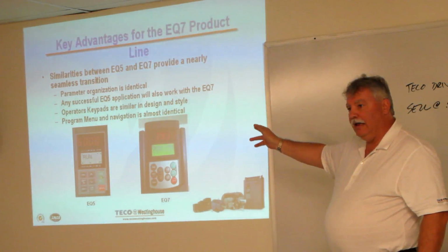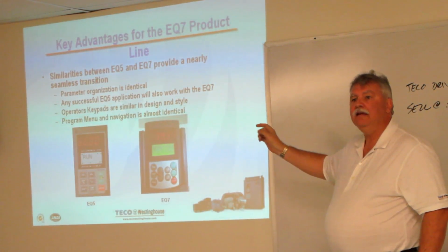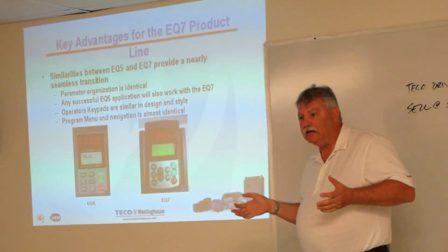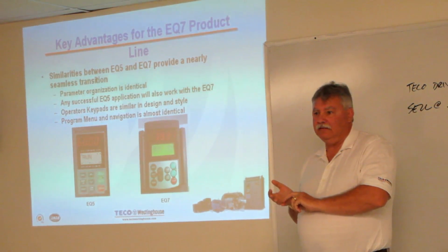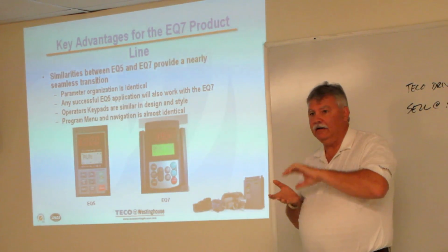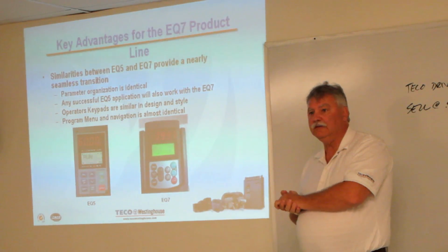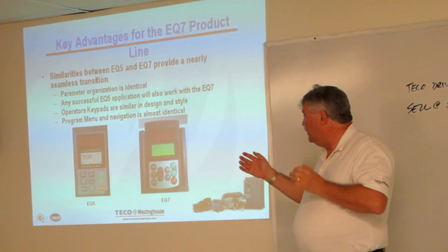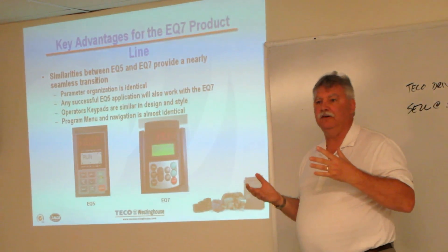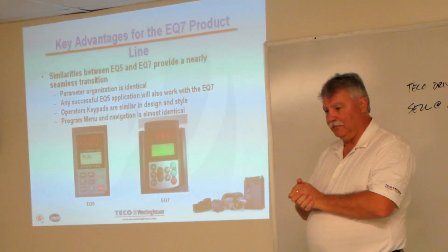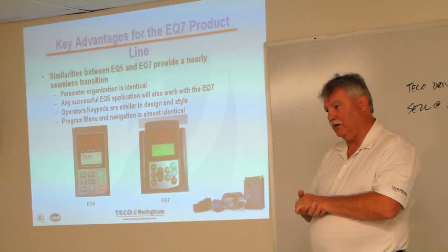If you're running along and you get a fault and the drive trips out for whatever reason, it takes a snapshot right at the time of fault of the conditions it was operating at, so you can retrieve, let's say, what your commanded speed was, what you were actually running at, the amount of amps you were drawing at that time, the relative voltage levels, the I/O, and it will do this for the 4 most recent faults. So you have fault history data there, something you can look at that's pretty reliable to help you decipher what's wrong with the system.